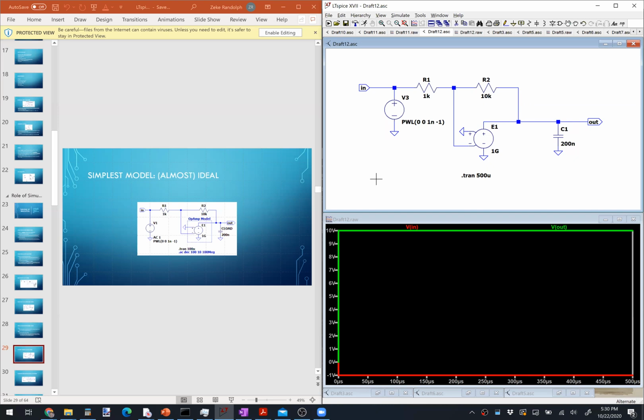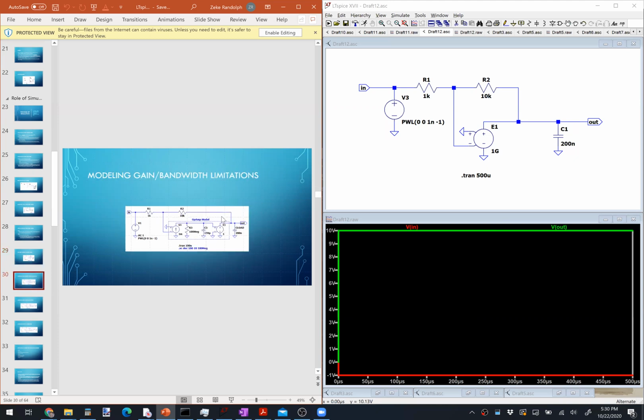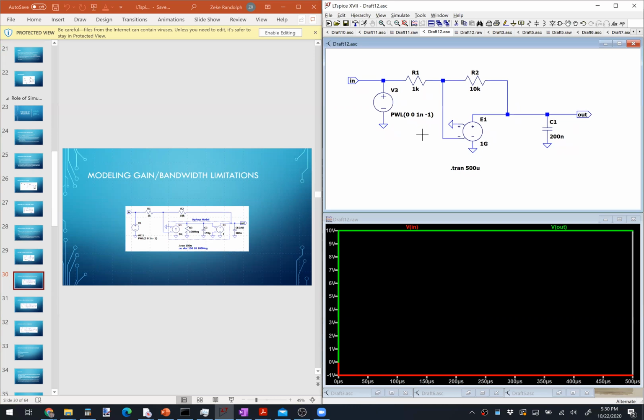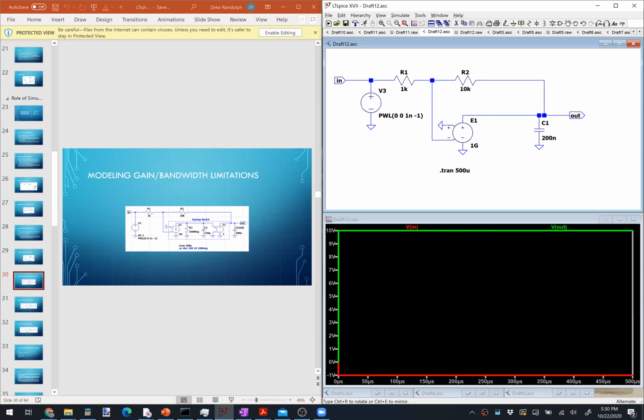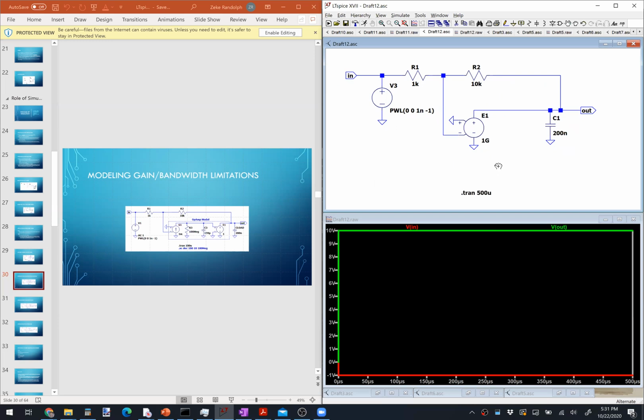Let's make the model a little bit more sophisticated. Perhaps we can find at what level of sophistication the circuit starts to see behavior that we are not as happy with. So we can model some more complex behavior. I'm going to model the behavior of an op amp that takes into account its limited gain bandwidth product. This is a topic that you'll get into in Engineering 442, which is your op amps class, if you haven't already. So instead of just an infinite gain voltage dependent voltage source, we'll model a voltage dependent voltage source that has a single pole associated with it.